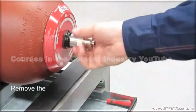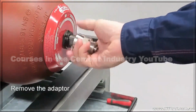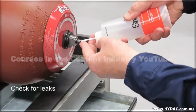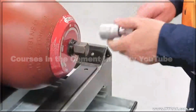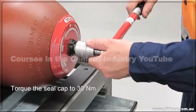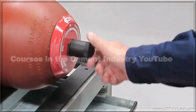Then remove the A3 adapter from the gas stem. Use a leak detection fluid to ensure that no gas is escaping from the accumulator. Replace the metal seal cap, tightening it to 30 Newton meters. Replace the plastic protective cap.